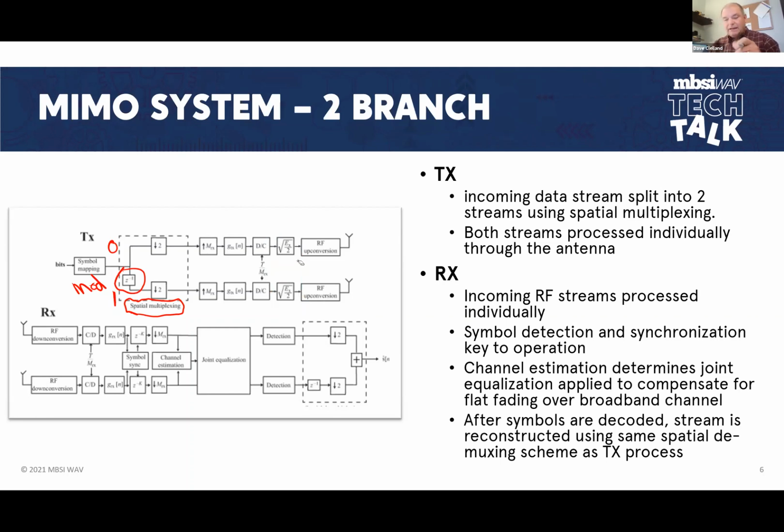It's definitely in an ASIC. Some of this may be hardware defined, some may be software defined, depending on the manufacturer of the equipment and whether it's a system on chip or an ASIC, but nevertheless the process is almost always the same. So we get the 2 antennas, and some manufacturers will transmit one on vertical and the other on horizontal, or maybe minus 45 degrees or plus 45 degrees on a dual slant antenna, which is typically the LTE standard. And so then we have our 2 streams on the air in different polarizations.